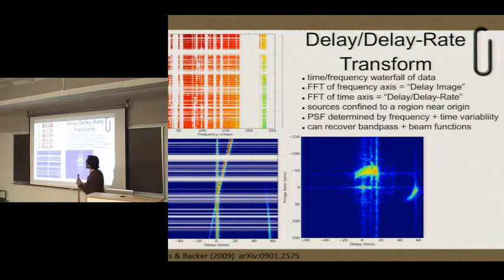And the problem is, any time you cut data out and you want to do a Fourier transform, you've lost information. You've introduced these sharp discontinuities in your data. So you need to bridge over those with some sort of interpolation, or if you take that Fourier transform with deconvolution. But that's actually a very solvable problem. You can deconvolve out the sampling pattern that you have here and really restrict these sources to the inherent spectra that they have.